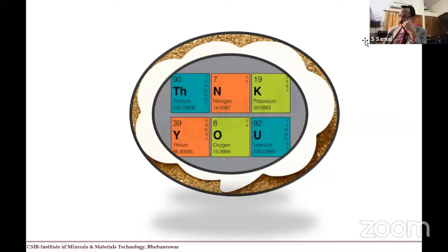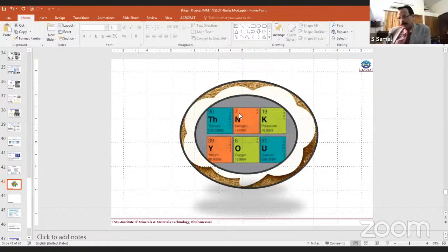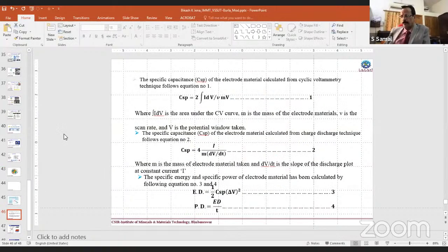Okay, may I put a question, Vikas? Yes, sir. I often face some difficulty understanding the extreme high values of supercapacitance, even close to 1,000. In the two-electrode cyclic voltammetry measurement, the amount of material deposited on the electrode matters. In the expression C equals IT by MV, the mass is in the denominator, right?